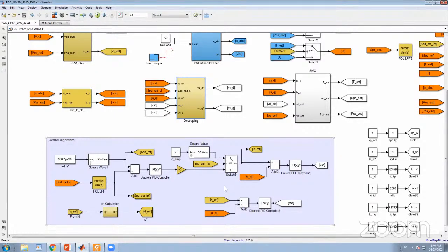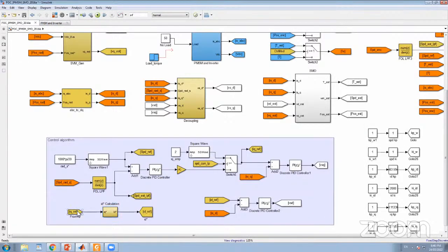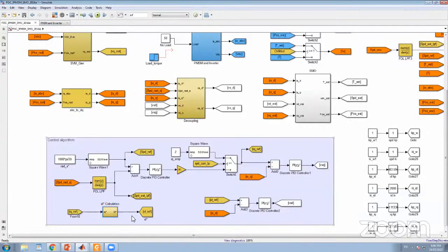As introduced in the lecture, we have 3 PI controllers: the speed controller, IQ controller, and ID controller. This module only includes the MTPA trajectory, and it is written in this block. Based on the IQ, what is the ID, for a certain speed, using the MTPA trajectory calculation equations.